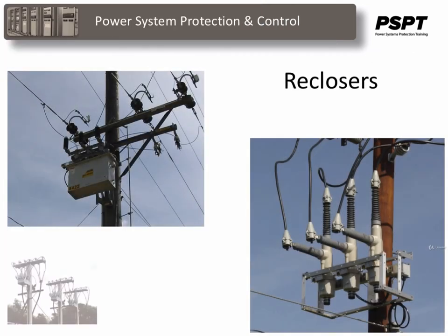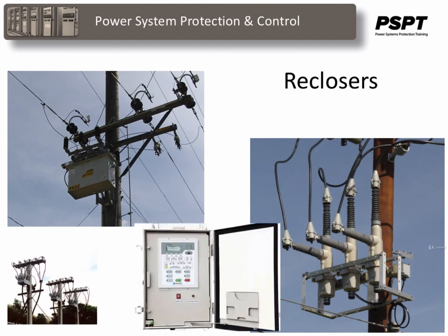A recloser is an overcurrent protection device. It is a self-contained overcurrent device for automatically interrupting and reclosing a distribution circuit or feeder. It has a predetermined sequence of operating and reclosing followed by a lockout. The recloser may be preset to have up to 4 operations before lockout, and those operations can be any combination of fast or instantaneous or retarded in time trips.